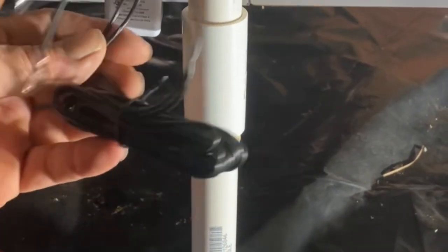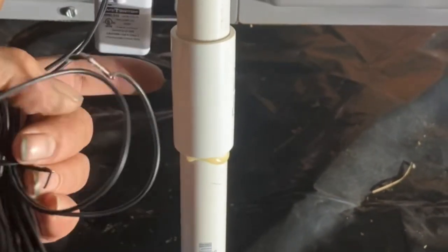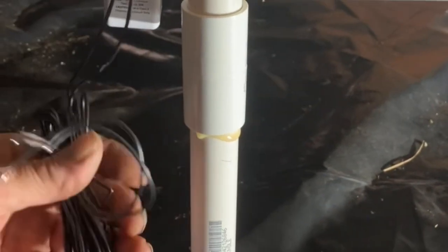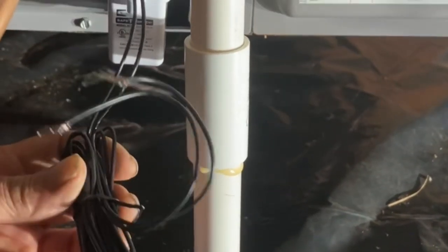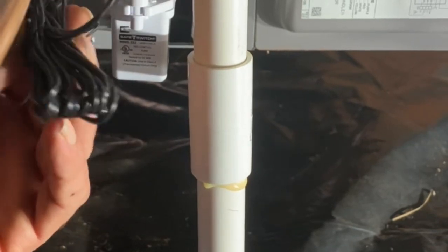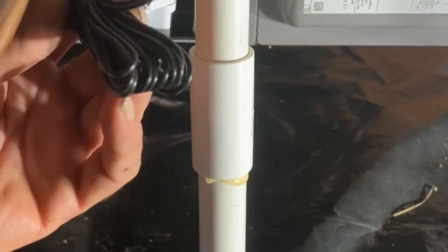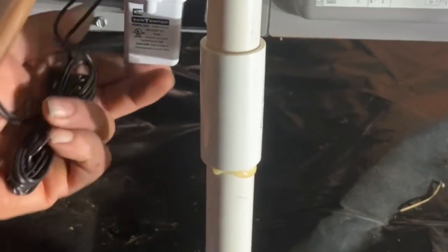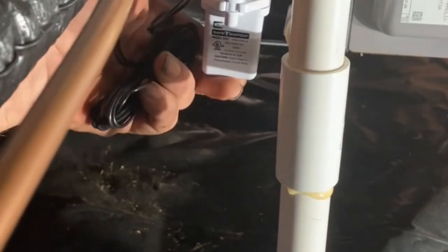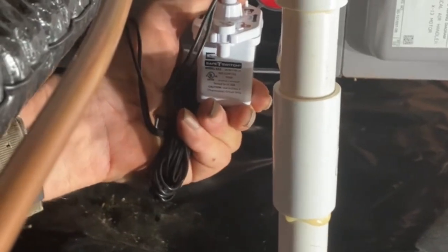This is an auxiliary drain switch. For some reason, if this drain gets stopped up, to keep from putting water all under the house, it wires in series with your control power. So if it gets water in this switch here, then it will cut your air off to keep from getting a bunch of water under your house.